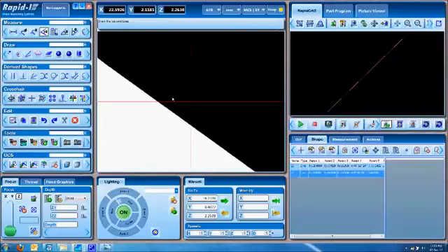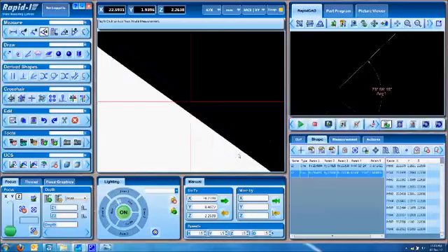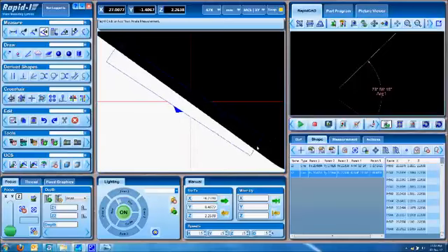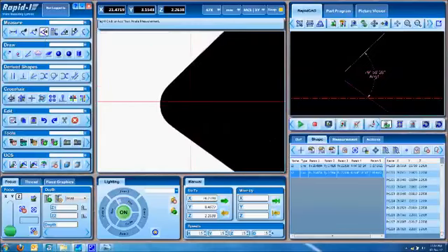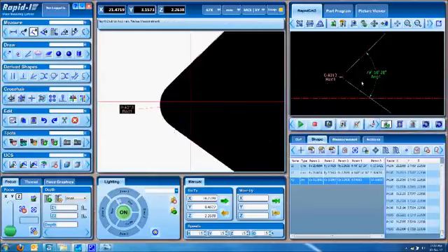Once we are ready for the next line, we just right click and click again to generate the next box. The moment the two lines are done, the angle measurement comes up automatically. So you click to extend it, the angle updates itself, and you're done with the angle measurement. To do the corner radius, go to the corner radius, click at the start of the arc, the end of the arc, and change the direction and click, and the radius comes up automatically.